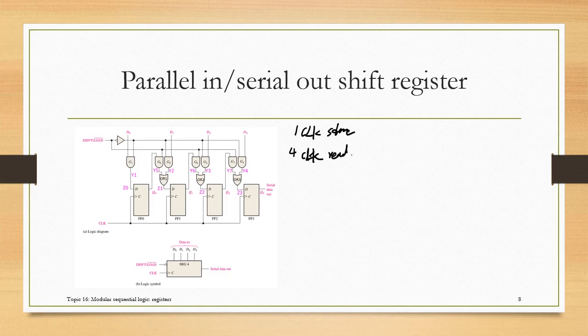We also need to separate the shift and the load function, so the data won't get messed up. From this input you can tell if we input a 0 here, it should load. Let's see how this works. If this line, shift/load, is equal to 0, it should perform the load function, but let's see how it works. So if this line is 0, which means we have 1,